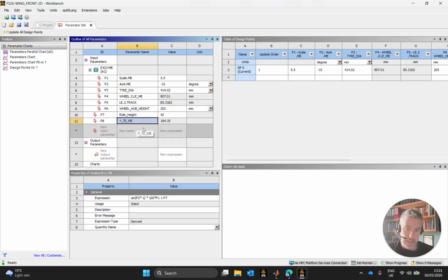Not only was this one really so that I could confirm that I didn't go over the 250mm Formula Student regulation for a front aero element, but when I have detail on the X and the Y, it can give me a point from which I could relate the leading edge of my first flap, for instance.